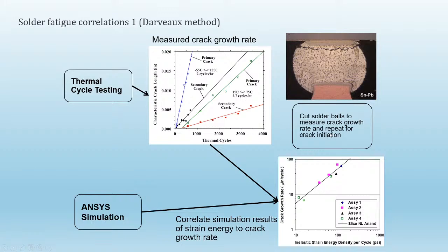He also did this for this idea of crack initiation. So in the beginning, in some cases here, it took a few hundred cycles. He also has data on how many cycles it took for a crack to start to grow. So this tells you that, maybe in certain conditions, your solder is just very robust. It won't crack because there's no crack for it to grow into. So this is the most accurate and most obviously complex set of experiments that was done.